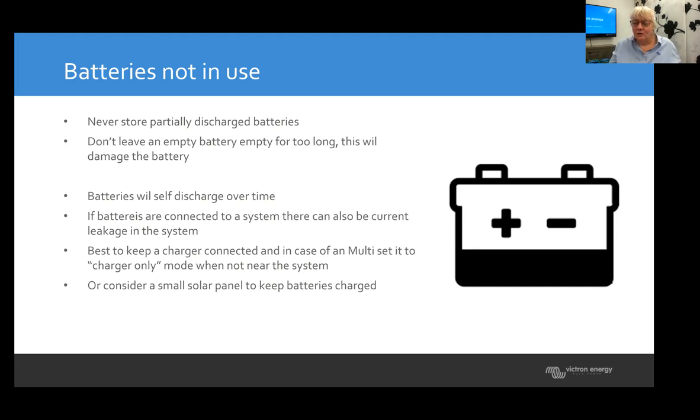So after a week of storage, we do 1 hour or so. Sometimes you can set it, but by default it's 1 hour. It will do repeated absorption that stirs all the electrolyte up. So it mixes the water and the sulfuric acid again, and then you can go again.